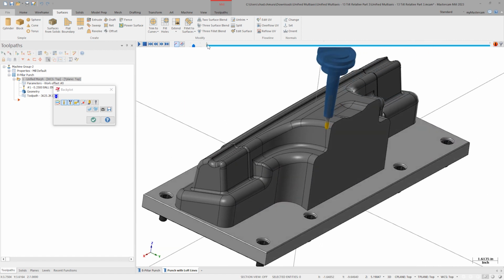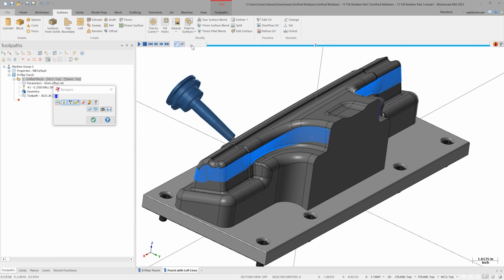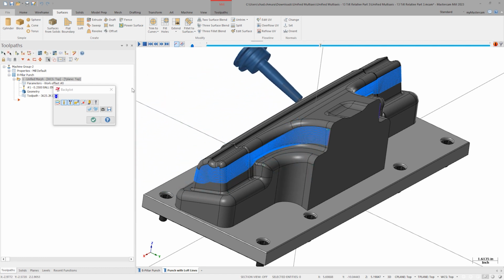The tool tilt motion in this operation is extremely clean, flowing much more smoothly than the motion created by the line strategy. It's also worth noting that the tilt relative to reference surface option has been added to the Convert to 5-axis toolpath in Mastercam 2023.